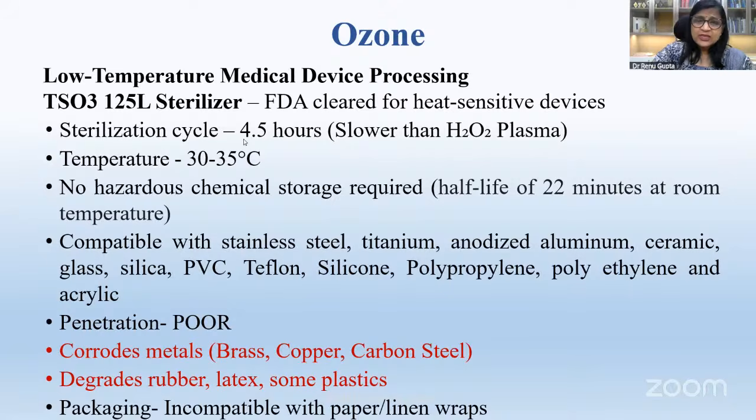Temperature is cold sterilization, 30, 35, 40 degrees centigrade. No hazardous chemical storage required because it is generated from oxygen and water. Half-life is 22 minutes at room temperature. It is compatible with stainless steel, titanium, aluminium, etc.